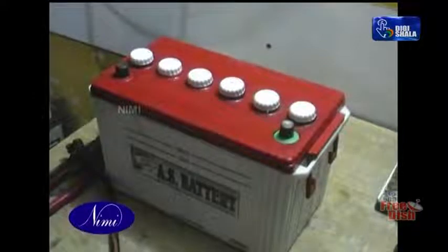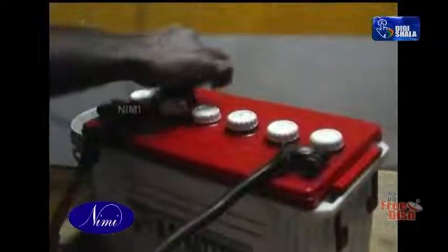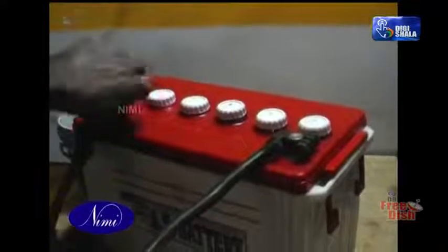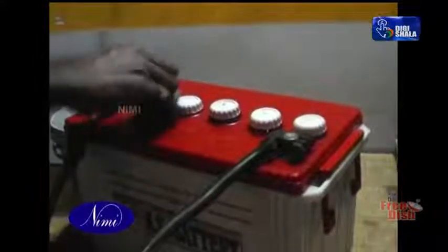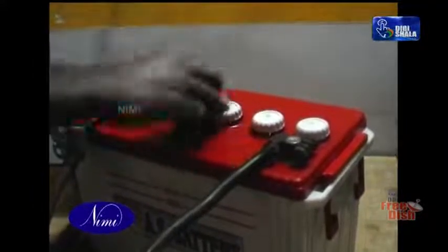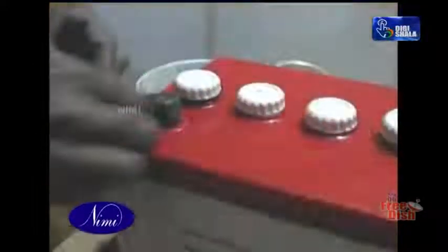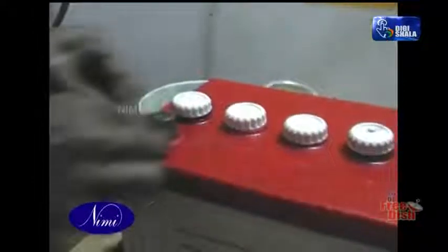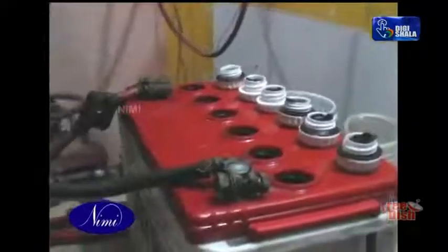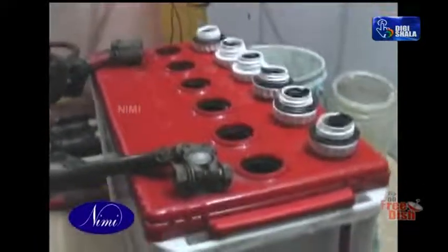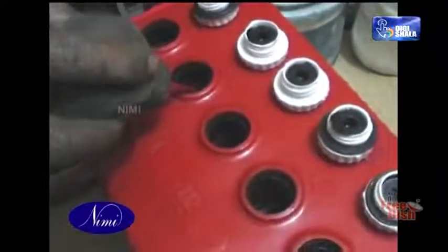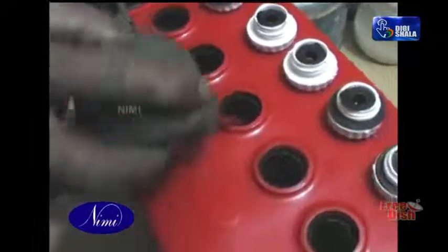Corrosion or rust on the hold down, on the terminal posts and the dirt on the battery should be cleaned using scraper and wire brush and a cloth soaked in ammonia or baking soda solution. Emery paper may be used to scrape the mating surface of the clamps and the terminals. The electrolyte levels in all the cells should be checked. If necessary, distilled water should be added to bring the electrolyte to the recommended level.